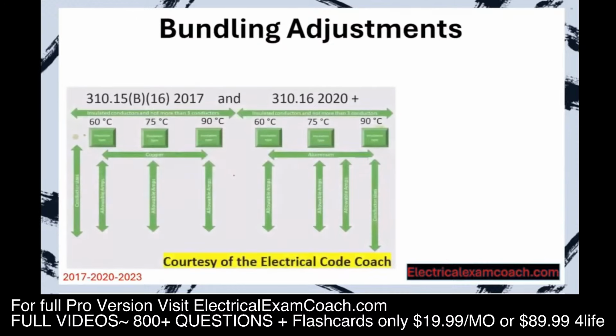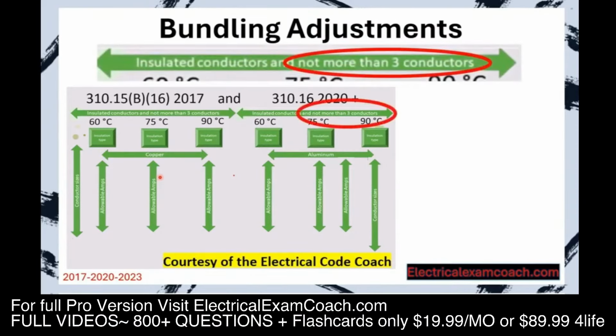Let's take a look at our primary ampacity table. I want you to turn there now. And these values down below this table are true if, well, the question is if what? If you look at the paragraph above the table, the one that I said we would come back and look at later, it's got some parameters there. It says, these are the ampacities of these conductors if, and the first if that we're going to look at is if there are not more than 3 current carrying conductors inside of a cable, pipe, or even buried in the earth together.